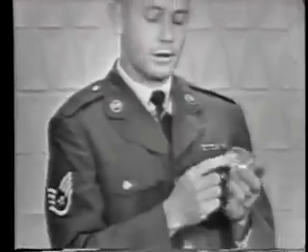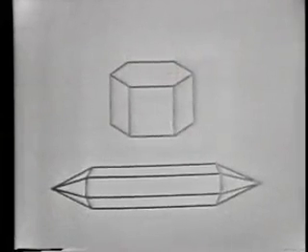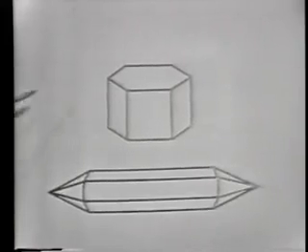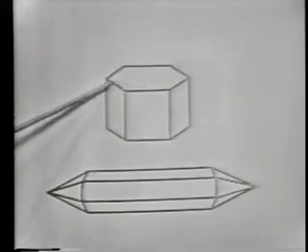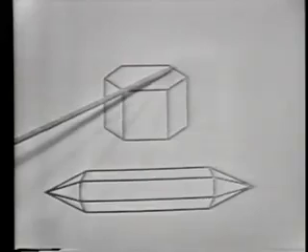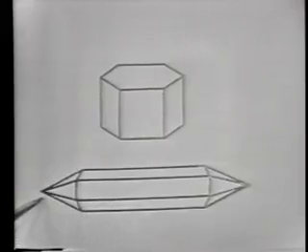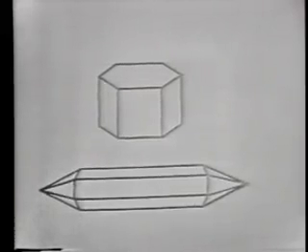Now, let's take a look at this drawing so that we can determine more about the quartz crystal. There are 2 views. The top view indeed shows us that the quartz crystal has a hexagon shape, 6 sides, while the lower view points out that indeed the quartz crystal in its natural form does have pointed ends. Quartz crystal in its natural form cannot possibly be used in oscillator circuits. It must be cut in a specific manner to exhibit its piezoelectric properties.